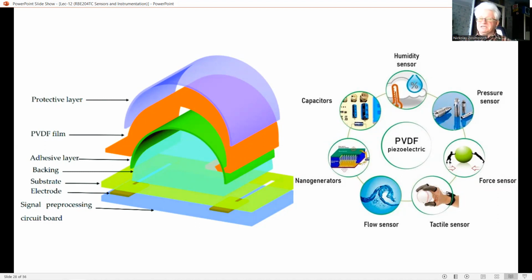Clearly, the small thickness of PVDF, as well as its flexibility, makes the sensing material an excellent candidate for this task. It is shown that an embedded PVDF layer provides useful information about ice debonding stress and propagation.